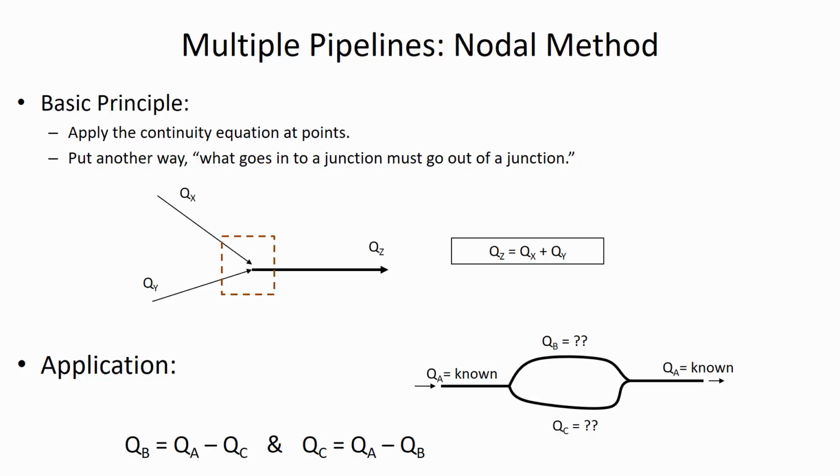We can write the flow rates in each of those two unknown pipes in terms of the other pipe, which is unknown. And the whole reason for this is we're going to try and set up systems of equations where we have two equations and two unknowns. And this is going to be one of our equations, the continuity equation, where we're going to remind ourselves that I may not know the flow through both of those pipes, the upper and the lower, but what I do know is that flow coming in equals the flow going out.